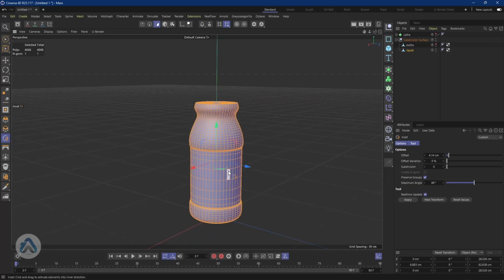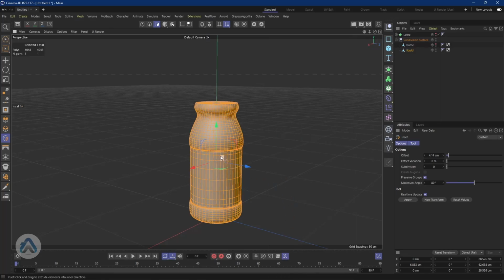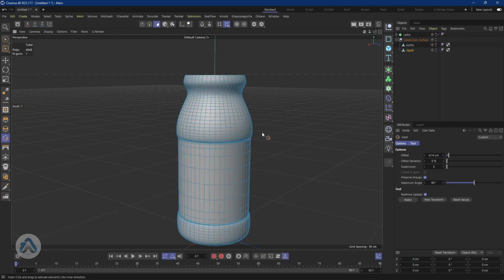When we say normals, they are the directions the object faces. So this is actually the back of the object, not the face of the object. I hope you understand it. So we right click, and when we come down here, we click reverse normals. Right now you see that the faces are not blue. This means that we have reversed the normals, and the normals are now accurate on this object. We go back to the object mode.